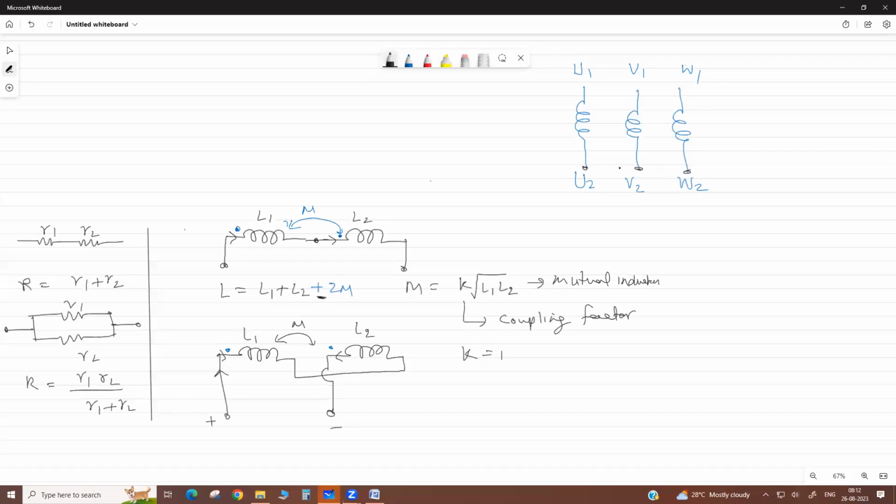Then this motor will sometimes not rotate; we do not get a constant torque. Same as in a transformer, the voltage is not induced because the fluxes produced by coils 1 and 2 oppose each other. That's why terminal identification is important. We fix the terminals, then we connect them either in star or delta. Got it? Due to this only.